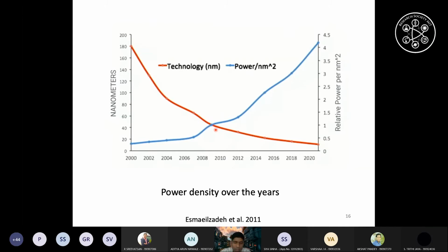Along with all this, it was thought that the power dissipated per area, the power density basically, should remain constant. Because if the power density increases, your chip will start heating up, right? If power density remains constant, then let's say your complete chip is emitting 5 watts in 1980, and in 2000 it is also emitting 5 watts. And in 5 watts it is doing more calculation. So that is very good. But we saw that that is not exactly what was happening.